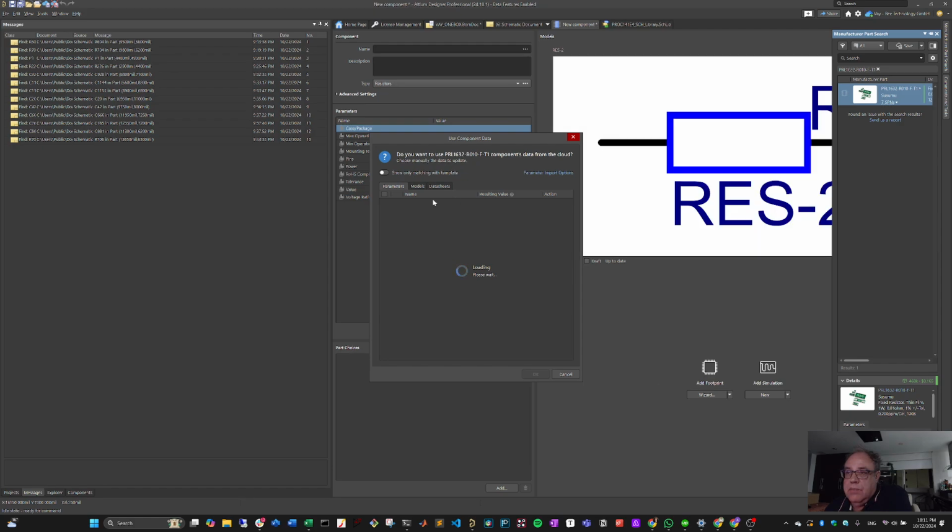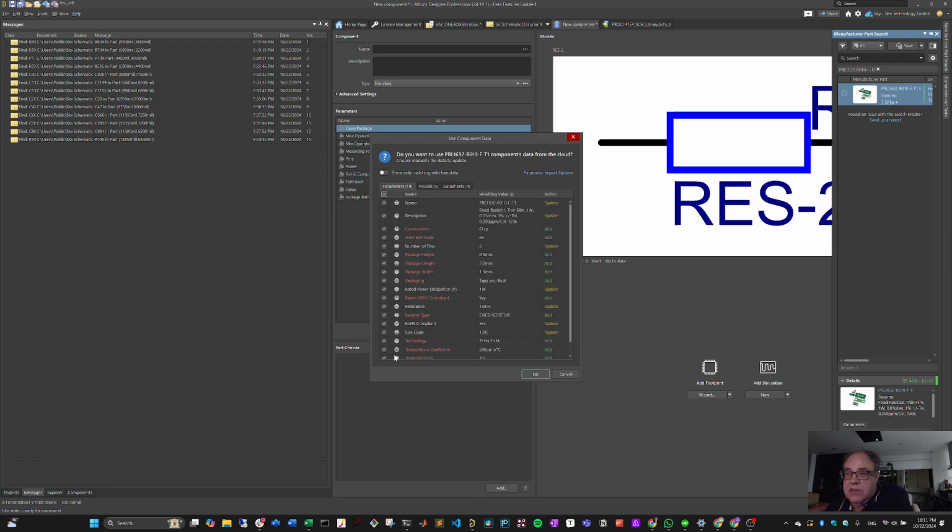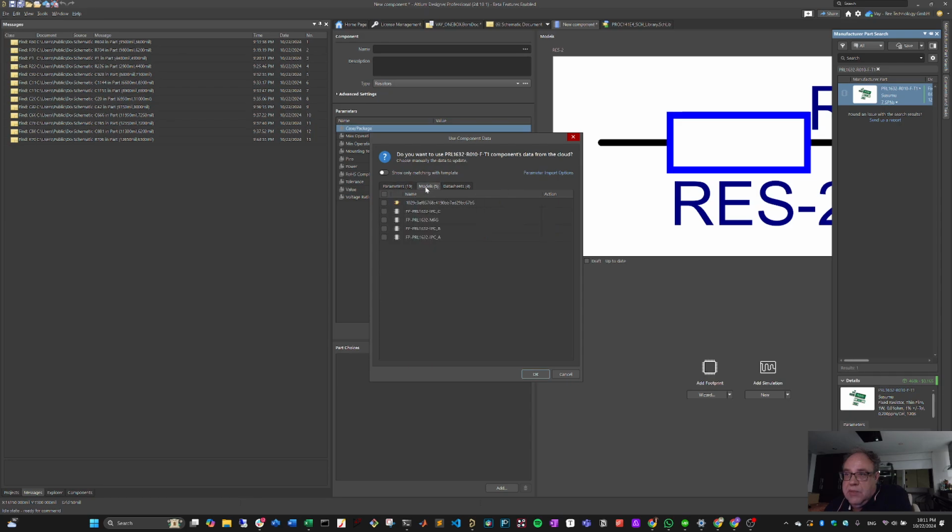And we have to wait a few seconds here for Altium to transfer the parameters. We want to check this entire list, right? So this entire list is checked. And then we go over to models, and we're going to check this entire list.